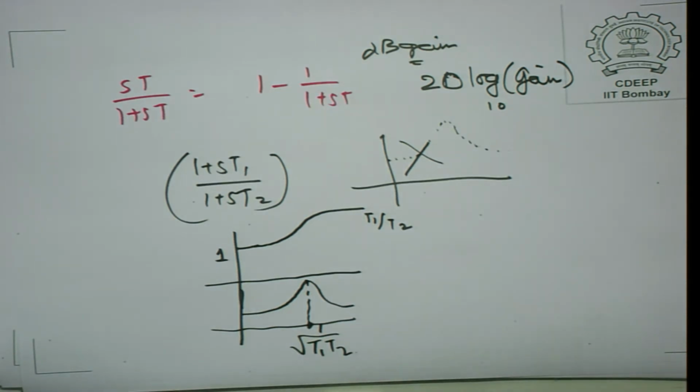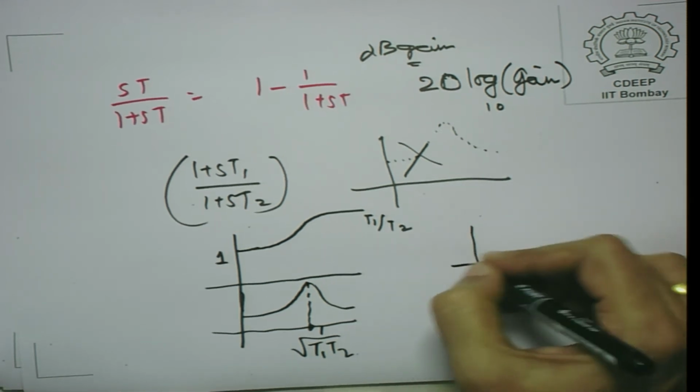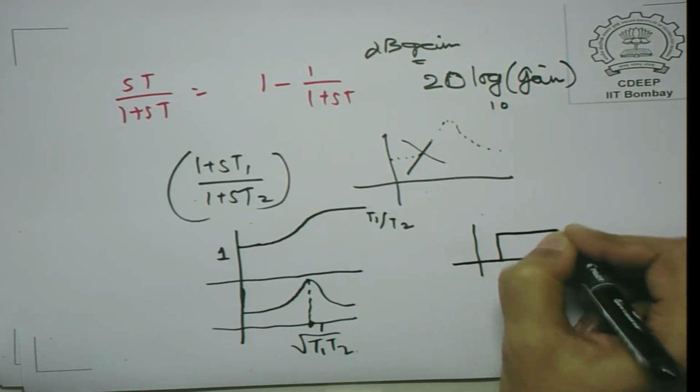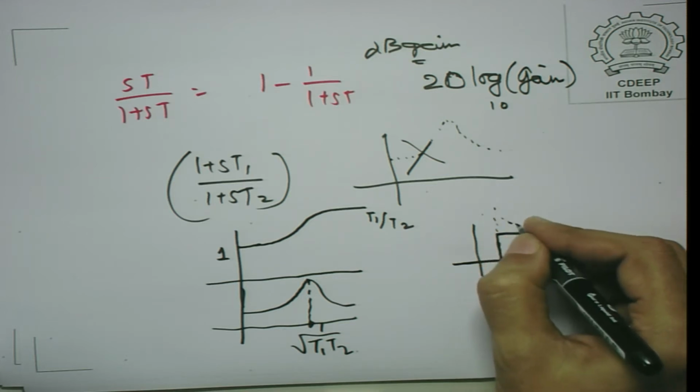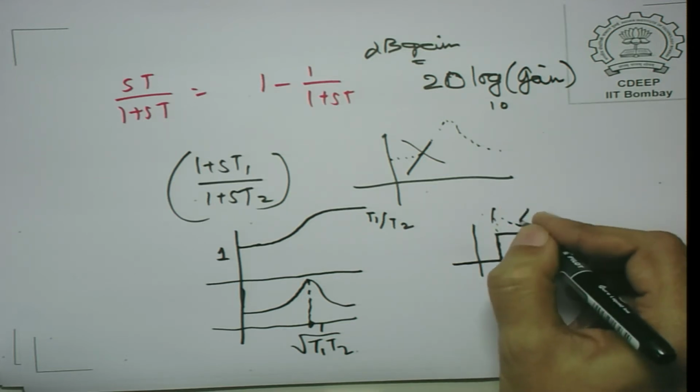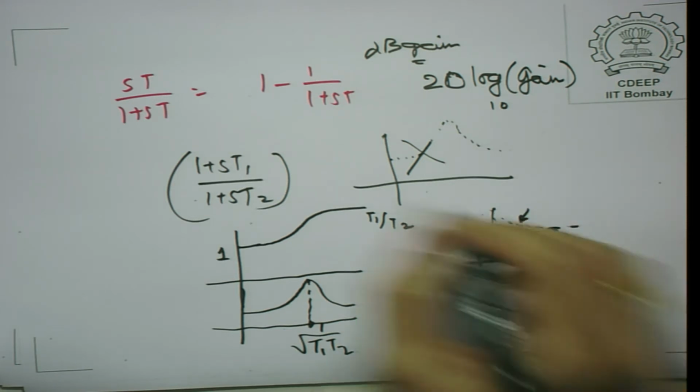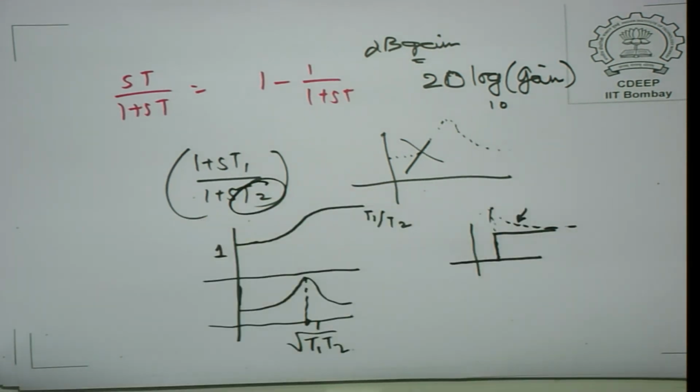Now, phase lead, as its name suggests, gives you a phase lead. If you give a step change to a phase lead transfer function, its transient gain is T1 by T2, which is greater than 1. So, you will find it goes up and goes down this way, and this decay of course is determined by the denominator transfer function. In fact, the denominator transfer functions are important. They are called the poles of the transfer function. The poles of the transfer functions determine the kind of decay rates which you see in the responses of the transfer function to say step inputs, etc.